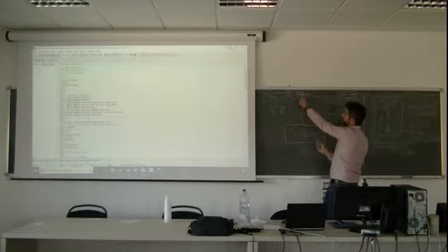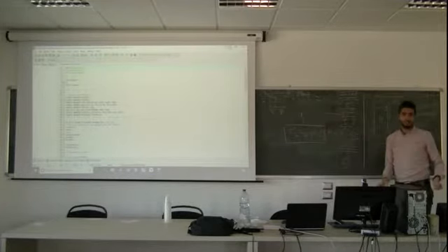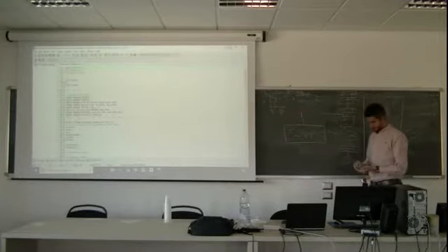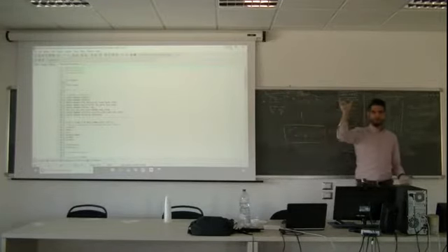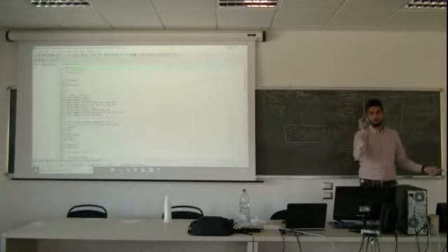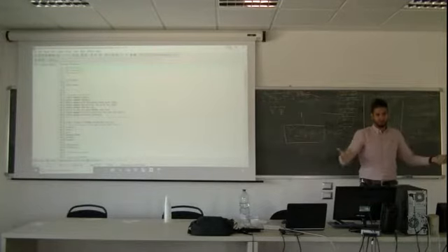So again, this has to be accomplished. West plus generated minus east will be 0. Right? Okay, we can compute this. What is QV? Remember, we change derivatives to gradients because that's the trick of numerical modeling. We assume the derivatives are gradients. So, because we are in a narrow region, the variation of this variable can be assumed as linear. Okay?